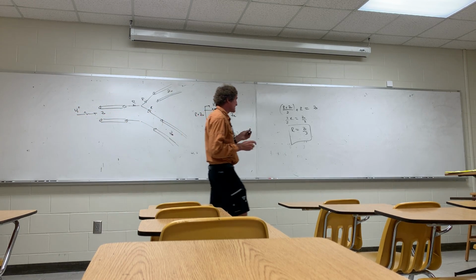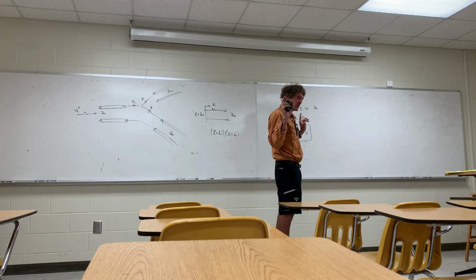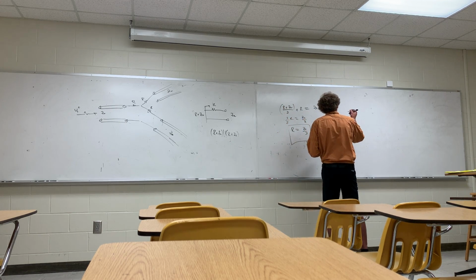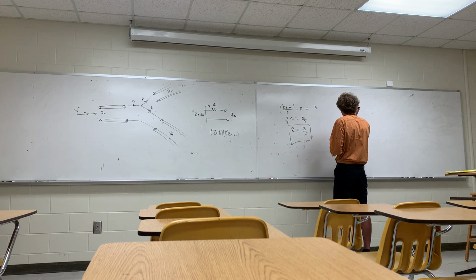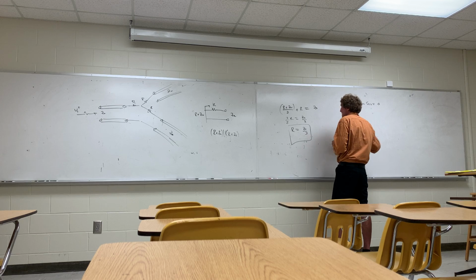So, that's what the value would be. Now, what are the S parameters then going to be? And this is again for just the splitter 2 ways. It's not a circulator, it's a splitter, so we want the S parameters. If you look at this, the first thing is S11 equals S22 equals S33, and that's 0, right?